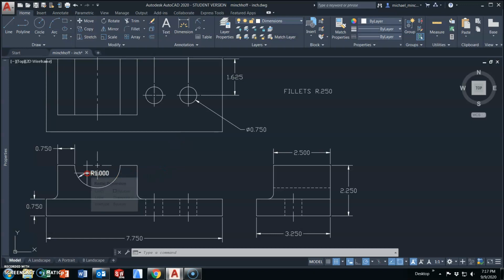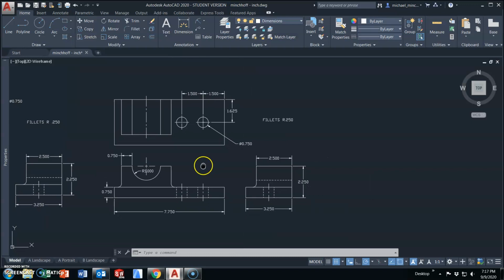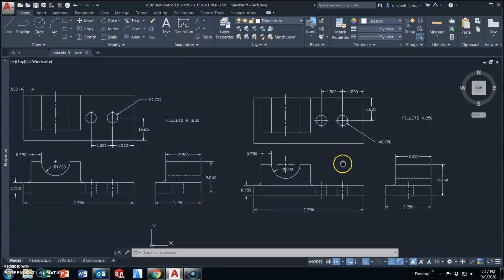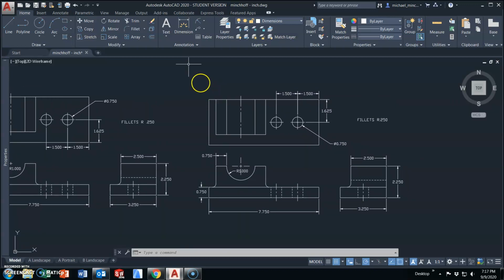So we have dimensioned radius, diameter. We've added a dimensioning note by adding a text box, matching the font size and style. Change the number of decimal places from 2 to 3 for this part. I've included all the dimensions. I have not double dimensioned. I am missing a dimension. Good thing I referenced my preliminary one.